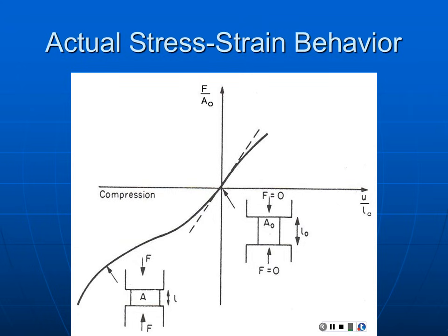And the problem lies with how we define stress and strain in this situation. If you think about the problem, in a compression test, as you compress the material, you started out with some area A0, but as you continue to load it, the area is increasing. So out here where I'm calculating a particular stress value using the original cross-section, that's not actually the cross-section that exists there. Similarly, in tension, the sample is shrinking. We're getting reduction. And so we're going to be off because of that.